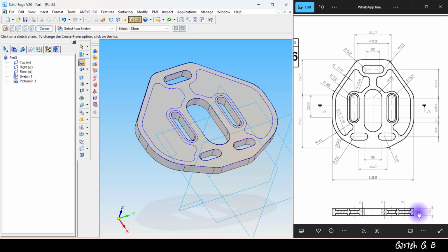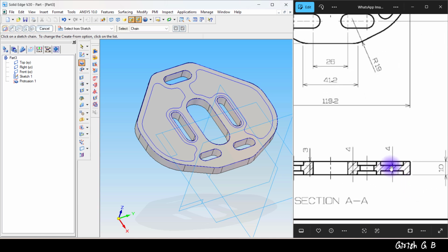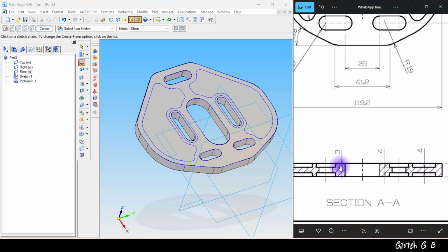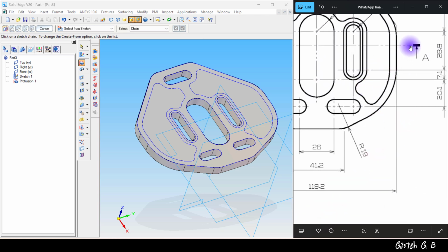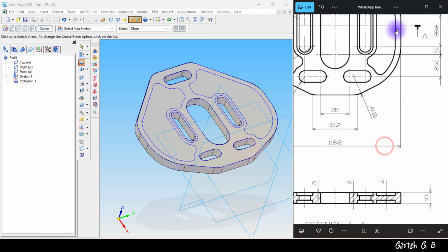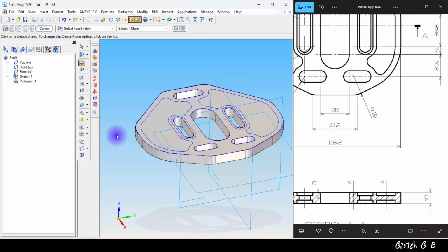As we can see here, it's a 10 mm total protrusion, but here inside it is 4 mm, and outside the depth is 23 mm. At section AA, when you compare it like this, there is a gap. There is a removal of material here, about 3 mm only. Remove 3 mm on both sides. So here also it is there. There's the entire hole, but this 7.2 mm diameter circle we need to remove for 3 mm.